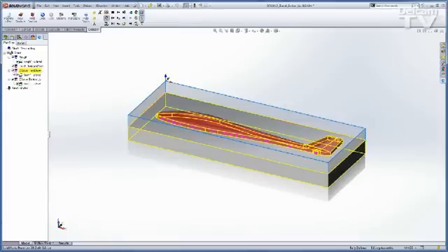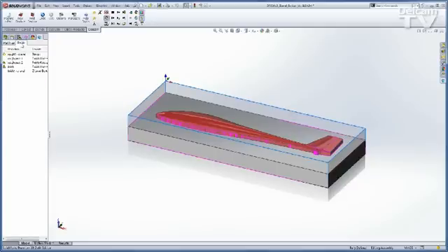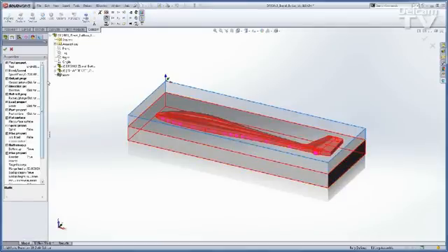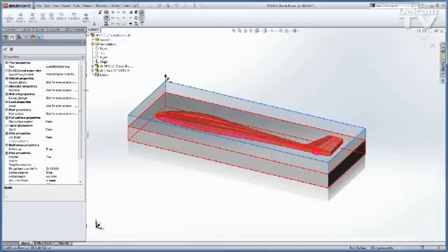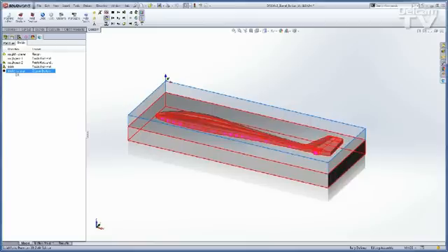The feature is identical. You just build another Z-level finish. But in the op list, you go to the attributes of the operation, and it's simply the bottom-up properties. Bottom-up, set to true. I'll stick another breakpoint in there and run into the simulation.